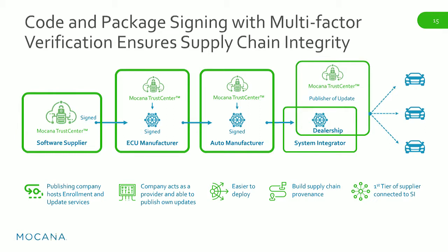So there's a long, multi-hop path of how it got from the developer to your car. And at every point, every entity would have signed the content, and so you know that the content as developed by the developer was not modified. Right, and the ECU has effectively the public keys associated with each of the signers, and as it receives that PKCS7 envelope, it can verify the package and then all of the signers before it installs it.